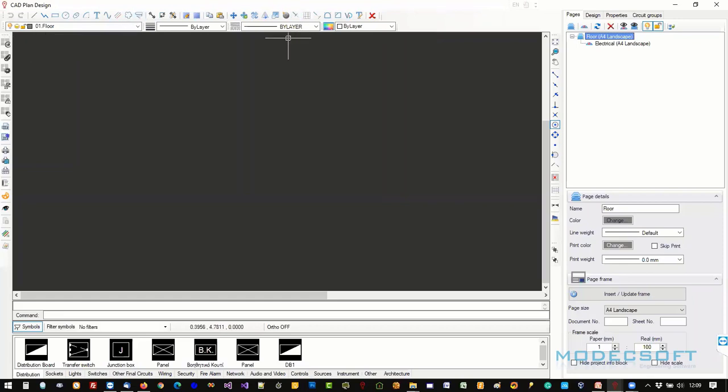And then we have other tools here, for example, which is to import external reference. So this is really important when you have an existing drawing, you want to import that into the software, and through that drawing, create your symbols, add your symbols there, place your symbols, and create your electrical schema plan drawing, which you want to deliver and measure things on it. And we have other stuff we're going to cover, of course, during the presentation, like bind the drawing, scale the drawing, fix the reference if you change the location of the drawing, and this kind of stuff.